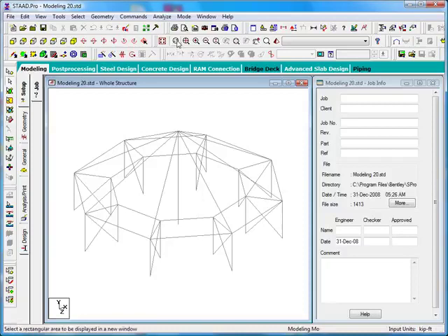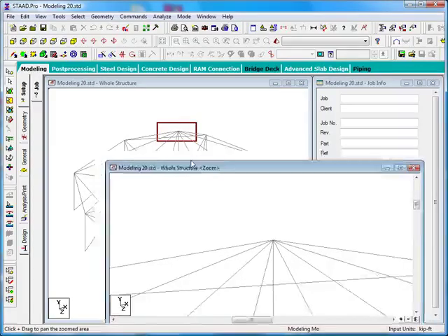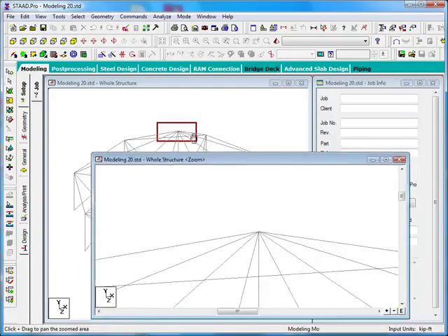The tool that's right next to it is dynamic zoom. The way that dynamic zoom works is I can click this tool and then stretch a fence around a particular area in this model, and what that does is it establishes a zoom window and automatically opens this new floating window here, that zooms in on just that little area.